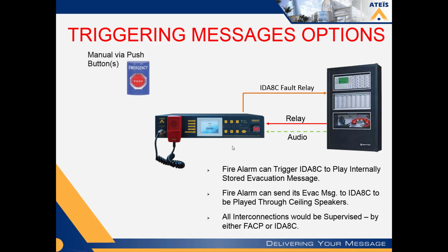Other ways that we could trigger and store messages are just manually via push buttons or any kind of trigger, because remember, as I said earlier, every one of these ID8 units, the controllers and the ID8S expansion units, have 9 logic inputs or control inputs. So we can have push buttons. They can be locking buttons, or they can be momentary push buttons. They can be all kinds of triggers. Maybe a severe weather station has a contact closure, or maybe you got door sensors or panic buttons or motion sensors. Any logic input that can give a contact closure or pulse, we can play a message or tell it to do all kinds of things inside the unit, even trigger an output relay if you want.